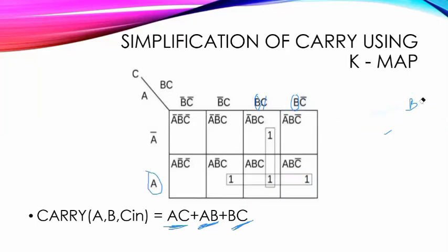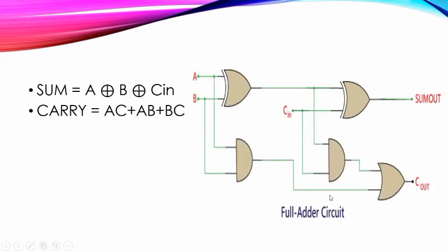And then how we will be drawing the circuit diagram, as I told for the last one. So these are the product and sum. If you can see, A and C are the product, for which we'll be using the AND gate. And for all these terms together, we'll be using what gate? The OR gate, right?